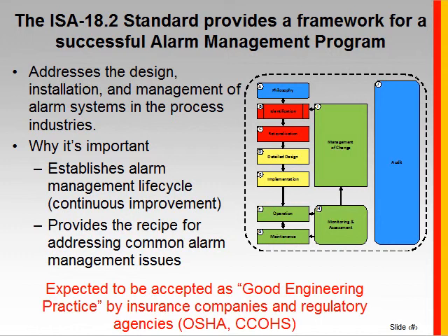It's organized along the lines of a life cycle, similar to the functional safety life cycle, which also leads to creating a continuous improvement approach. And as I mentioned, throughout the standard, one of the goals is really to provide the recipe or the direction for how to eliminate those most common alarm management issues. It's expected to be accepted as good engineering practice by insurance agencies and regulatory agencies such as OSHA.